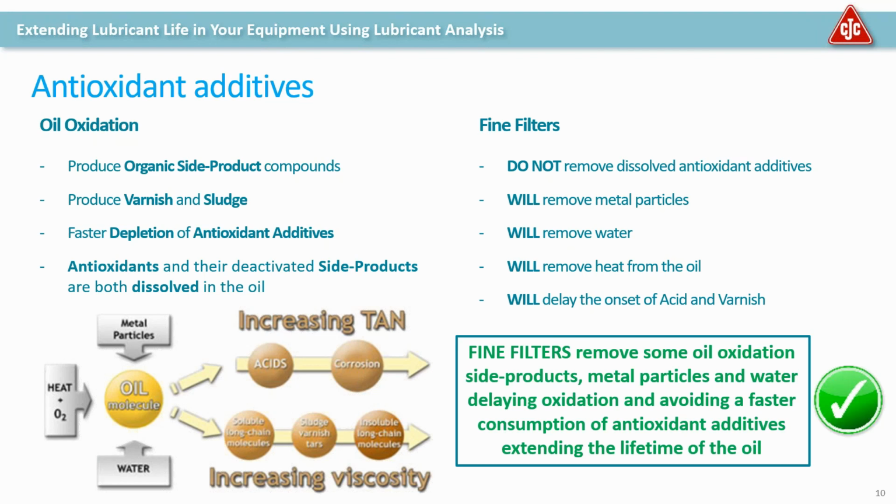And so we can conclude again that fine filters, they will remove the oxidation byproducts, they'll remove particles, they'll remove these catalytic type particles, and overall it helps to avoid the faster consumption of antioxidant additives, therefore extending the life of the oil.